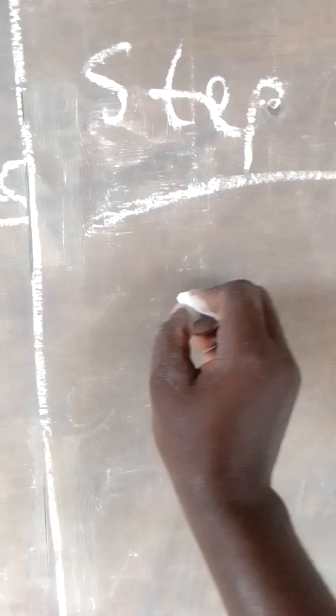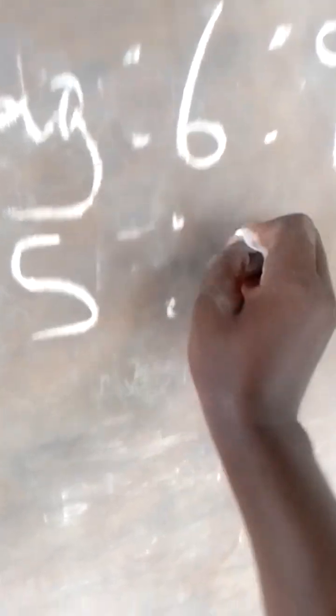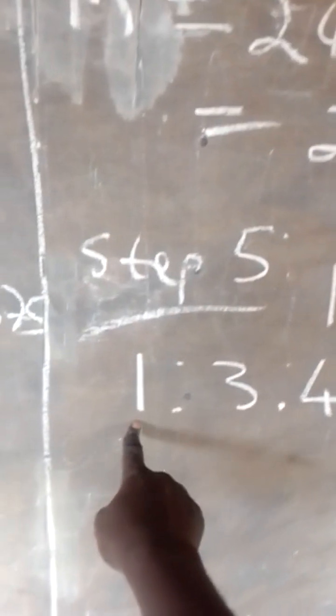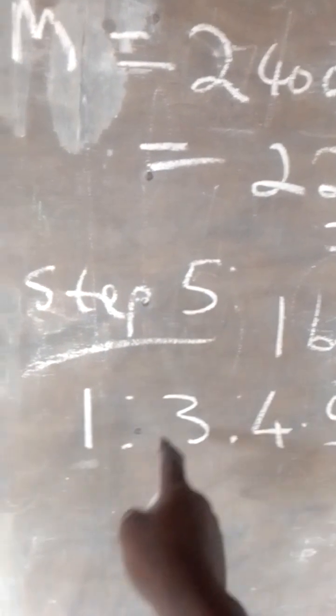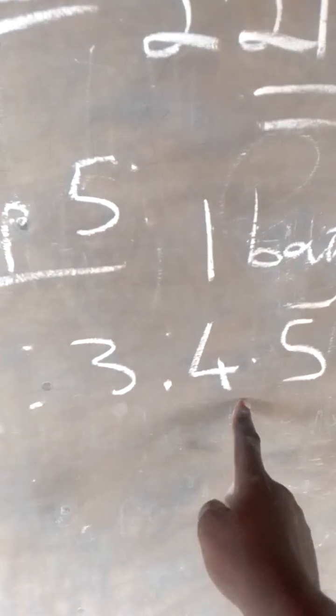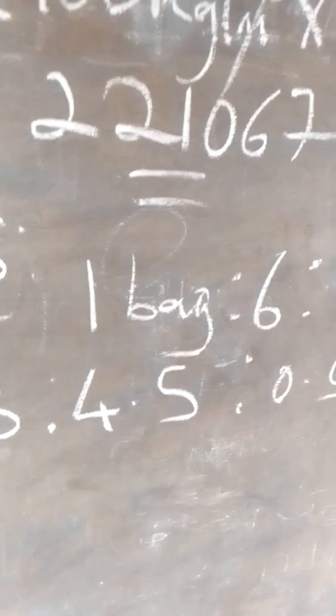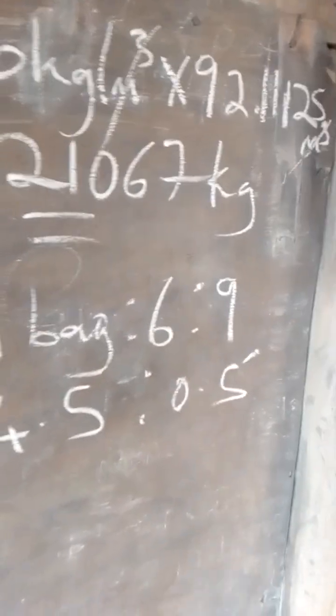We do it this way. We call it 1:3:4.5, and let me add water, 0.5. What this means is, in calculation, we always use half headpan of cement, 3 half headpan of sand, 4.5 headpan of chippings. 0.5 is just the water cement ratio.